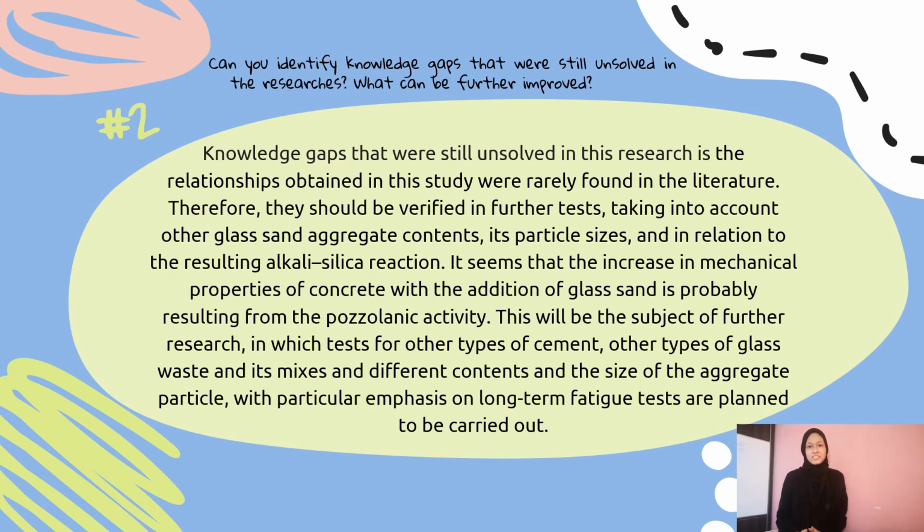Knowledge gaps that are still unsolved in this research: the relationships obtained in this study were rarely found in the literature. Therefore, they should be verified in further tests taking into account other glass sand aggregate contents, particle size, and the resulting alkali silica reaction. It seems that the increase in mechanical properties of concrete with the addition of glass sand probably results from the pozzolanic activity. This will be the subject of further research, in which tests for other types of cement, other types of glass waste, different mix contents and aggregate particle sizes, with particular emphasis on long-term fatigue tests, are planned to be carried out.